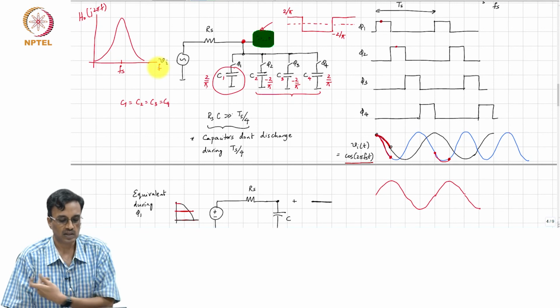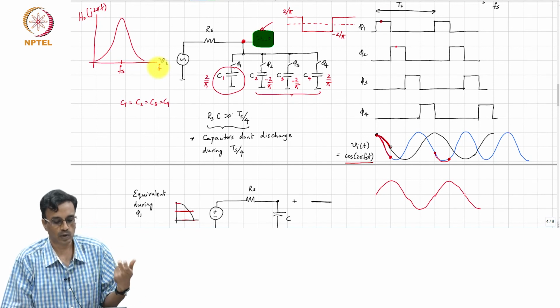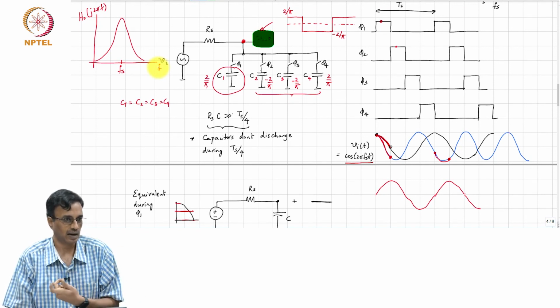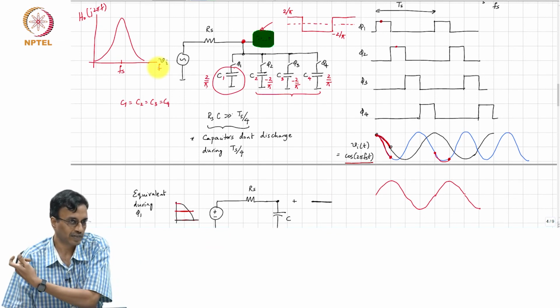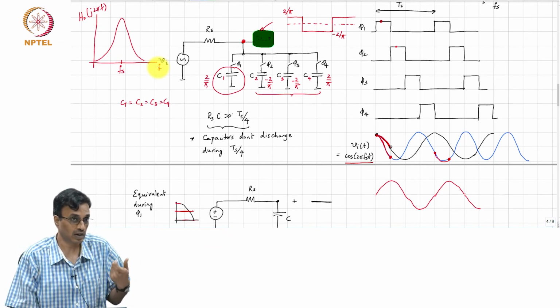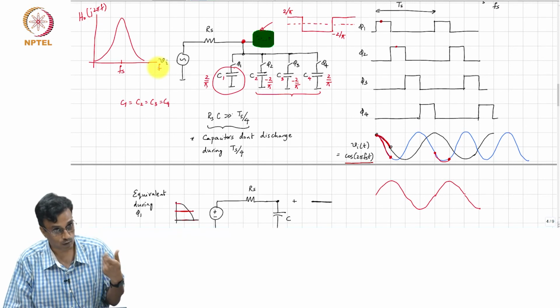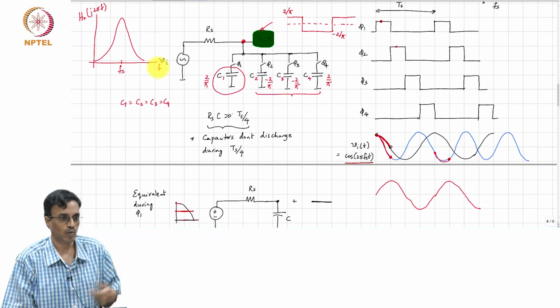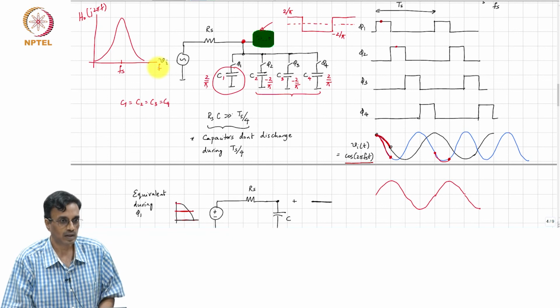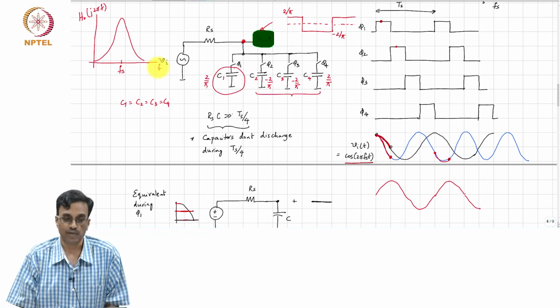If you divide the clock frequency by 2 using a digital divider, you have all of a sudden tuned the band pass filter's center frequency by a factor of 2, which would have been very, very difficult to do with an LC filter, correct?